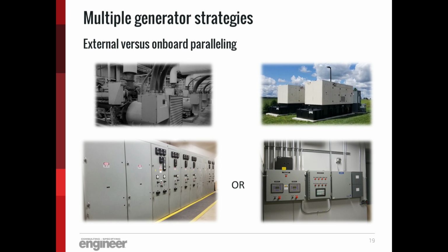Thank you. So I agree 100%. And that also relates to onboard versus traditional external paralleling gear. Your staff might be very comfortable with external paralleling gear in the big sections, but now they might want to save some space and move to onboard paralleling. Well, that puts the controllers themselves that have the logic on the gensets, and maybe that's not where they want to stand or where they're used to standing to operate systems. So you might need an alternate display or a copy of the engine generator controller inside a location, like I show on the bottom right.